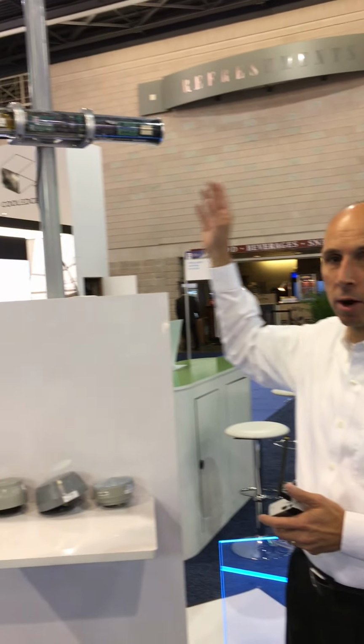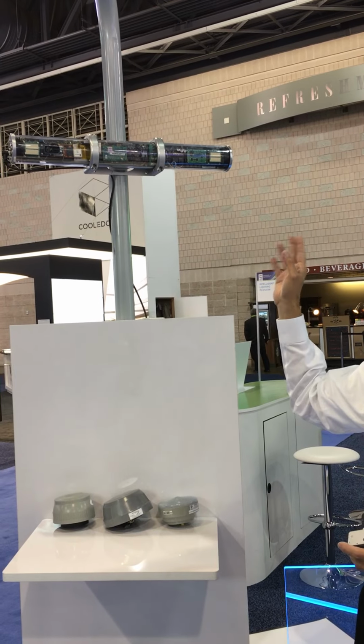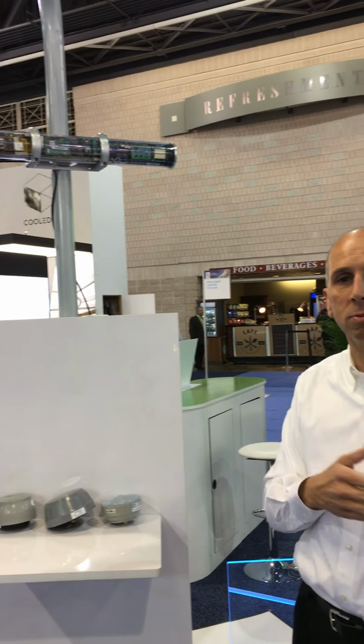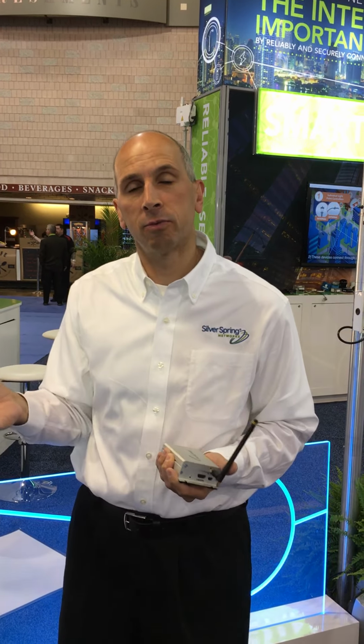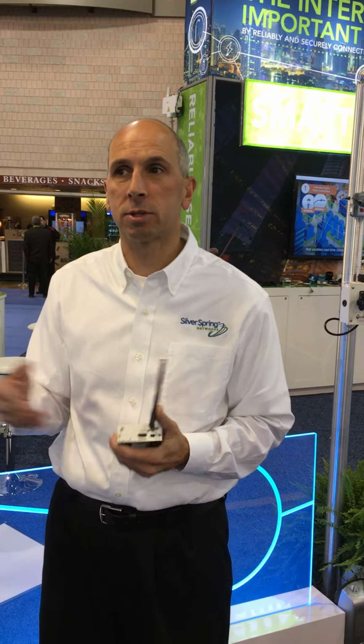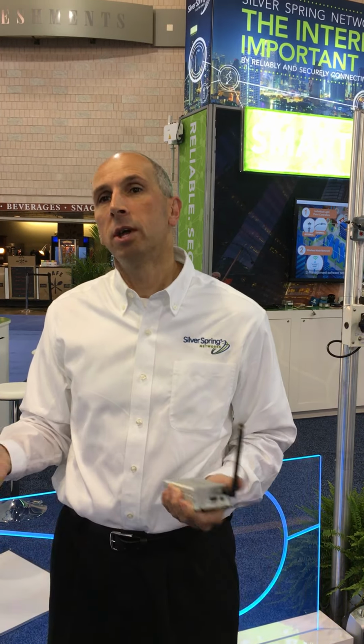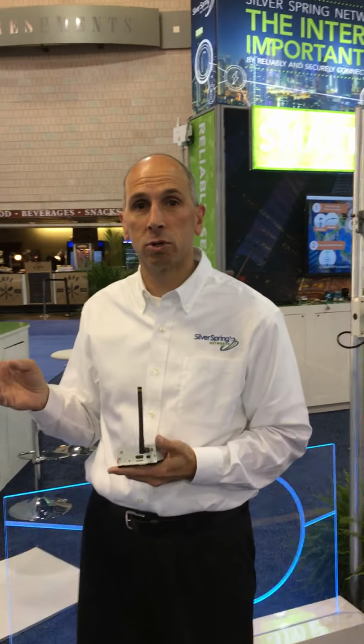And it uses radar. There's actually 2 radar sensors there to collect information about cars moving through the point of view. Typically this is done either through running a wire across the road and counting the cars as they go across it, which can only be done in fair weather and good weather times. Doing it during the winter months is hard. Or inductive loops are in the road. That's very expensive to install. So our partner here at Houston Radar has a good solution.